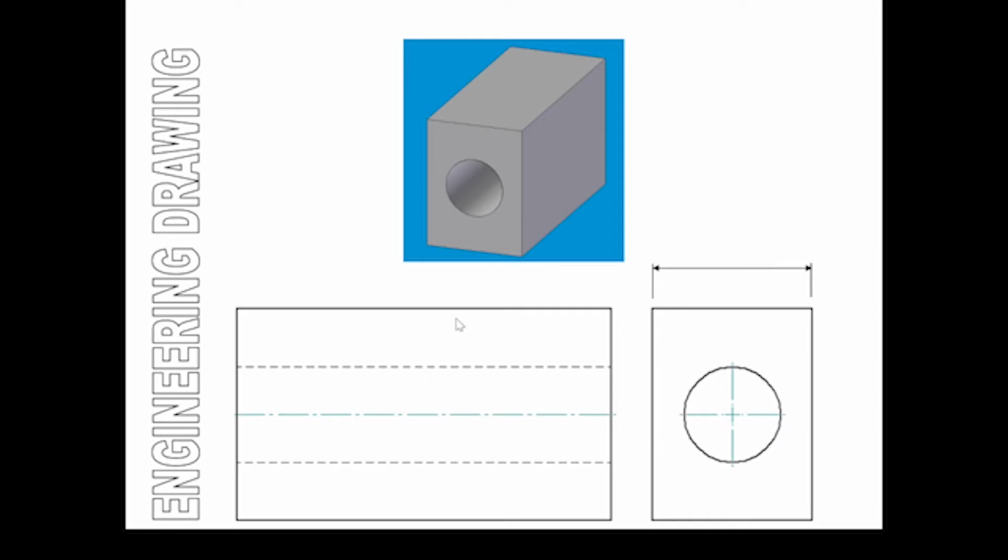Okay. Now here's an example of how you can use lines to show various details. So the solid line on the outside marks the edge of the block here, looking at it sideways. And also there is a cylindrical cutout, or a circular cutout, that goes all the way from front to back. It is shown using a dashed line.